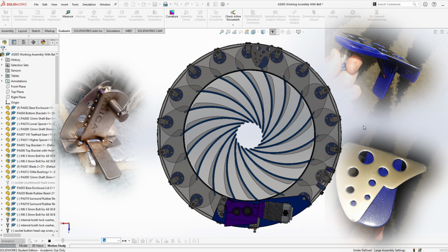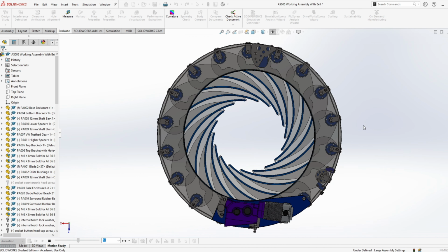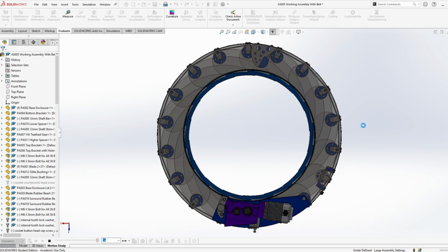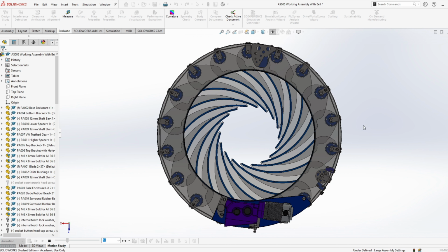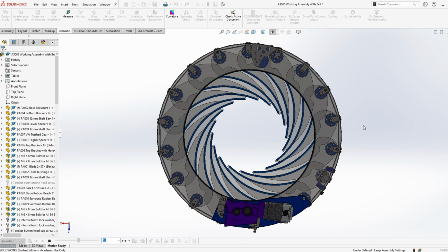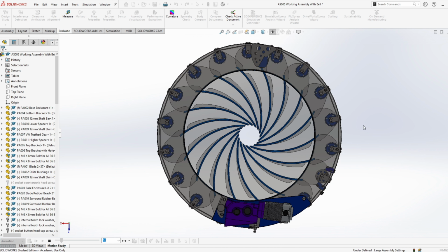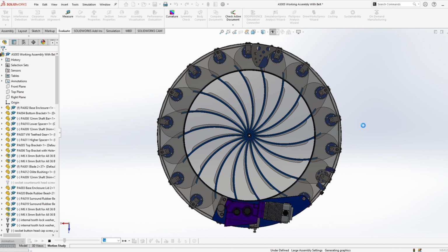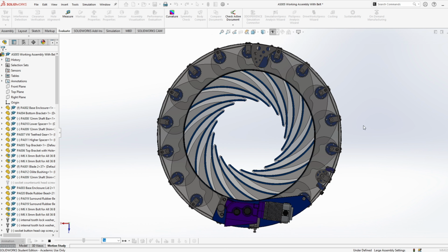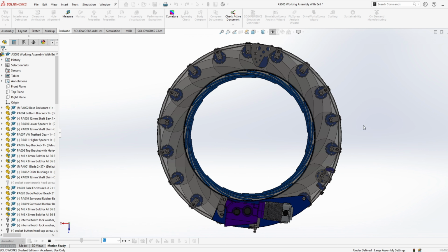The tensioner is used here to compensate for the larger belt size that could only be sourced at 3048mm, which was 75mm too big. Therefore, its main purpose is to remove a bit of belt slack, approximately 75mm, but it works well as it pushes the belt into the center of the aperture, just as the gearbox motor does on the opposite side, 180 degrees away.